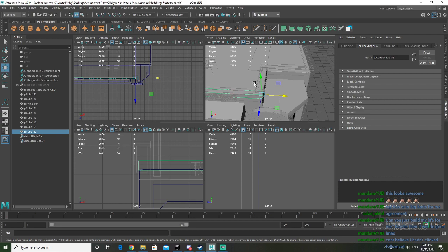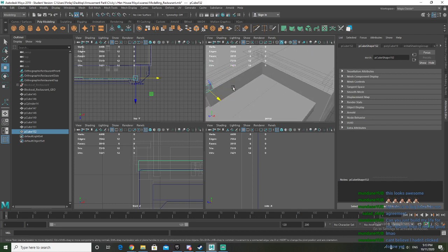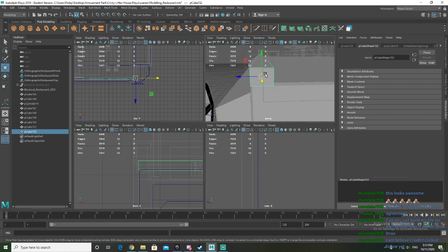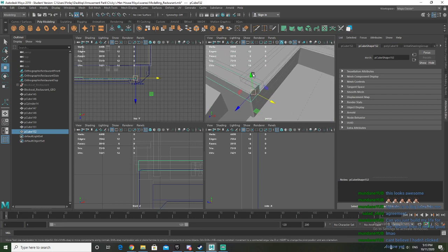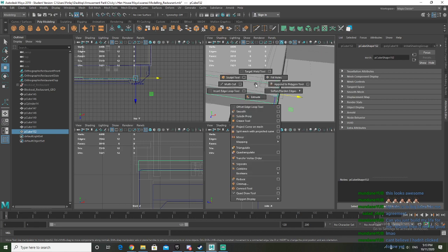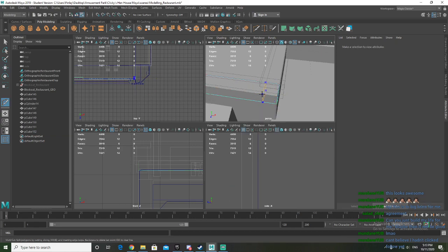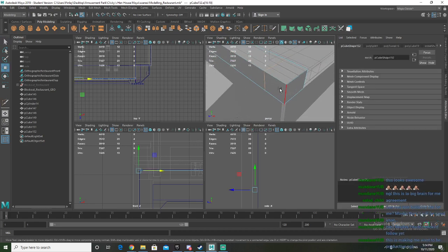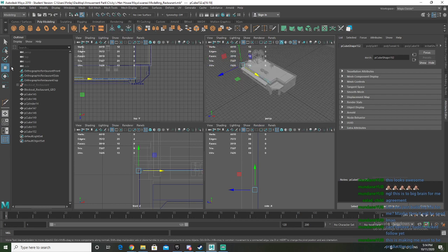we're going to select, make sure, figure out, yeah, what we're going to do is multi-cut, make it about as square shape as we can make it, like that. We get the edge tool. Want to make it about the same. Move these edges.